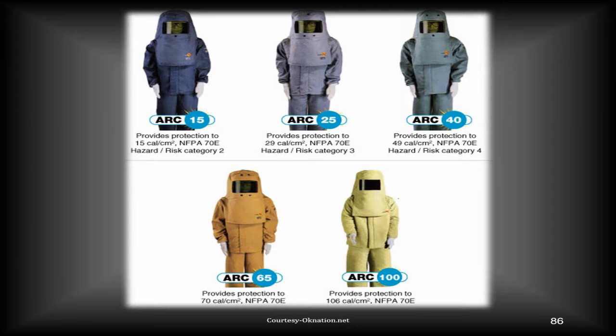And one thing that's very important to remember, and you could spread this on to your mechanical friends. Oftentimes when our mechanical friends are up on a rooftop or on a side of a building working on a commercial structure, or in some instances, depending on the area of the country, maybe even a residential structure, that is an elevated amount of voltage. So you got 480 volts. Oftentimes they're not wearing anything to protect them from an electrical shock.